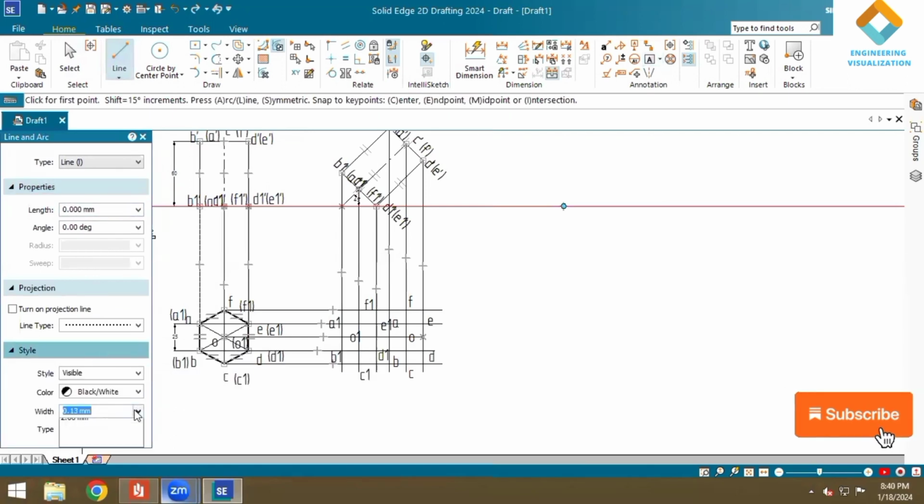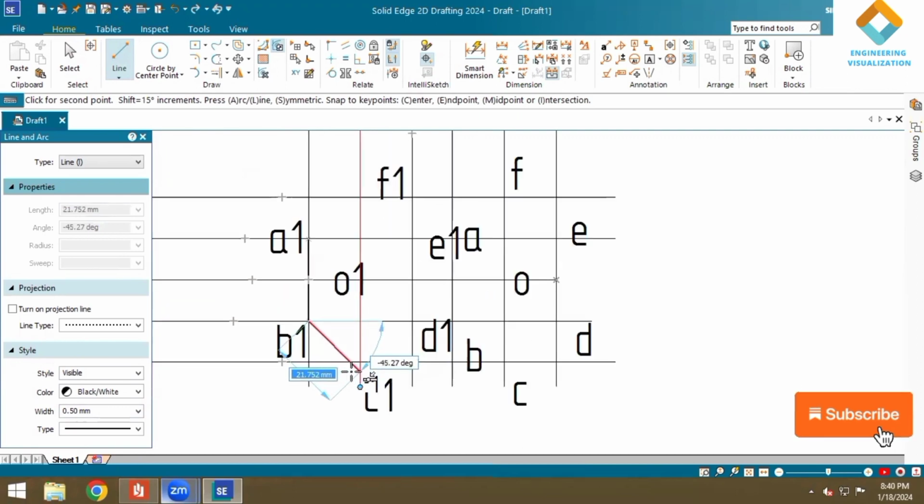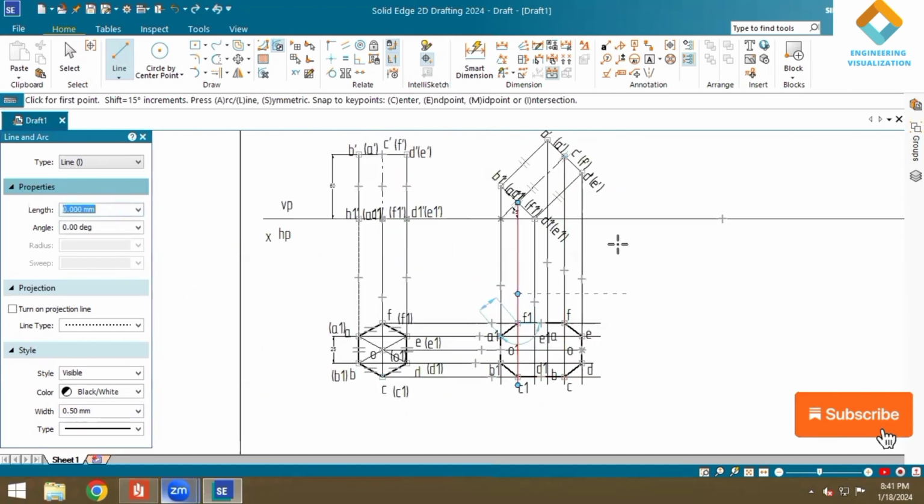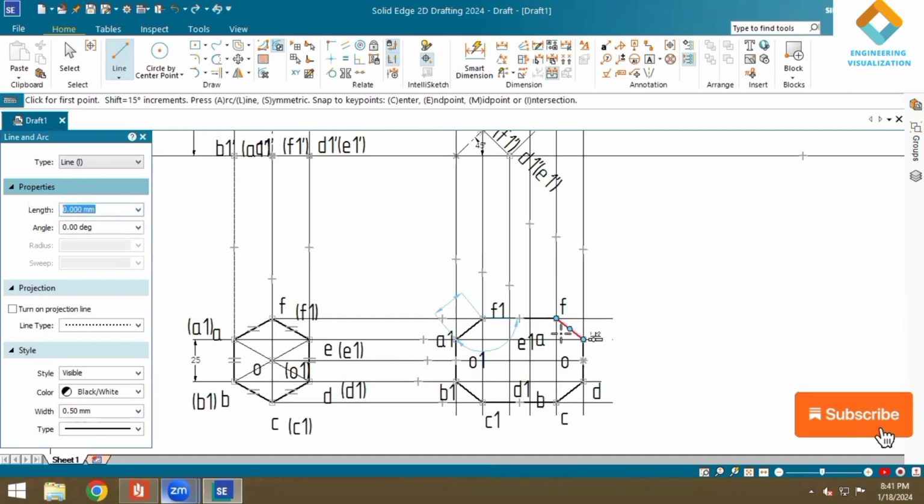To construct the second position top view, we know it has three steps. The first step is constructing an outer boundary line. Join all the outer points. Now mark the visible faces. The top face is visible, that means the top face hexagon is visible from the top view.